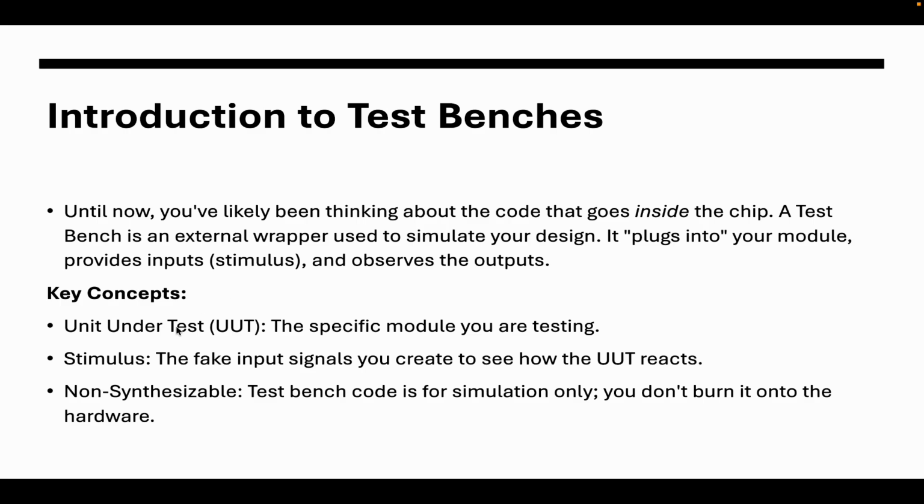The key concepts in a test bench: unit under test, or we also call it design under test (DUT). It means the specific module you are testing. The module is the design. That module is getting tested here. Stimulus: the fake input signals you create to see how the UUT reacts. It means you give a number of input signals to check what the output will be. Non-synthesizable: your design is synthesizable into hardware logic, but test bench code cannot be. It is just for testing, right?